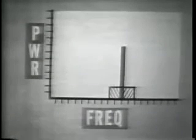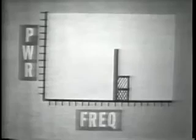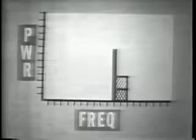Now, we have seen that identical intelligence is present in each of the sidebands. Since either sideband carries the same intelligence, transmitting both sidebands is a waste of frequency space. Since the carrier and one of the sidebands are not required for transmission, why don't we eliminate them and use their power to boost the remaining sideband? Well, let's see what would happen. We eliminate one sideband, we would narrow the required frequency spectrum by 1/2.